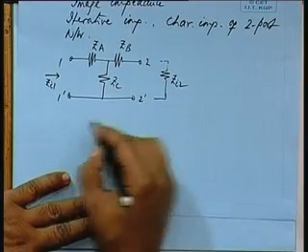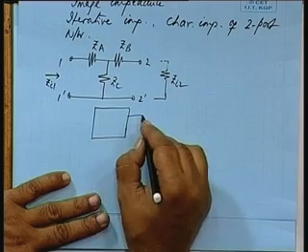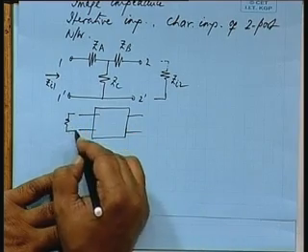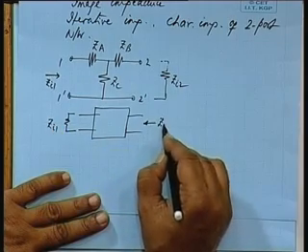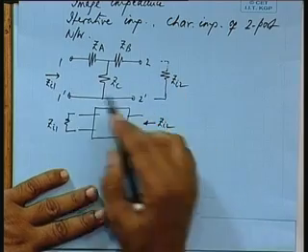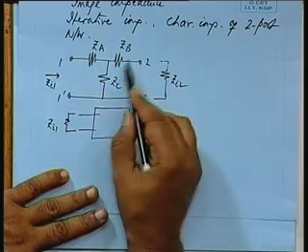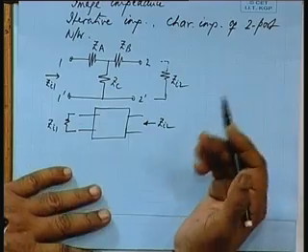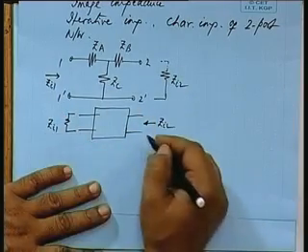and if I load this same network, I show the network just by a block. If on this side if I put ZI1, then impedance seen from this side is ZI2. Then ZI1 and ZI2 will be the image impedances for this network. So, for a general network where ZA, ZB, ZC are any set of values, ZI1 and ZI2 will be different. So, there are two image impedances.